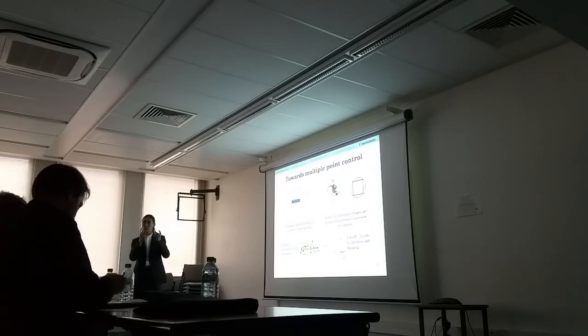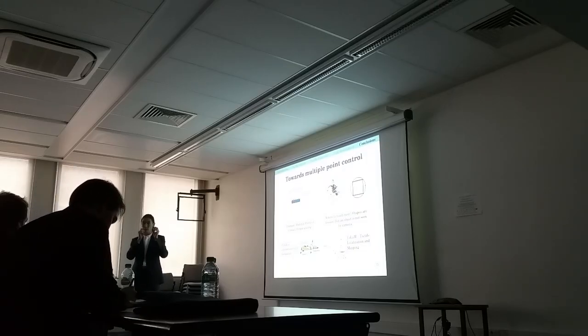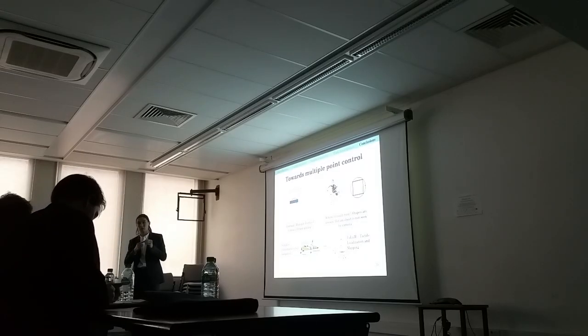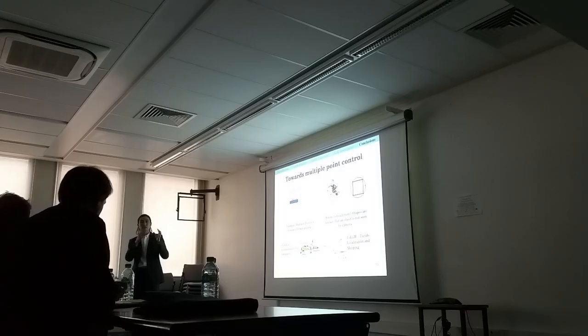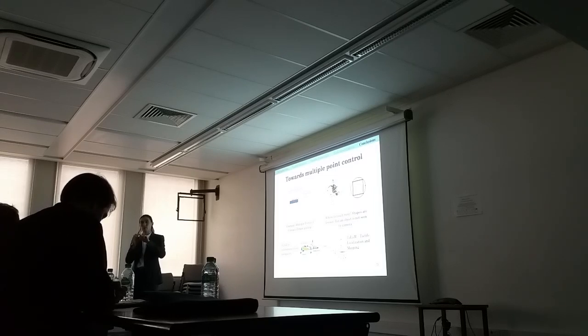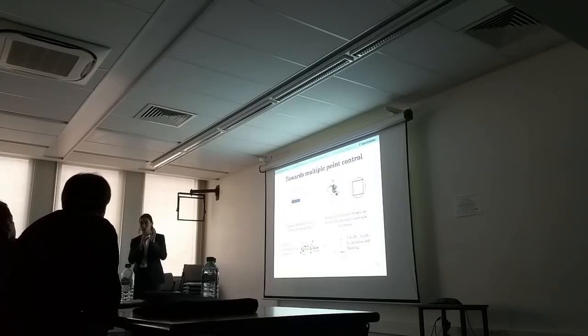Here we can map the center of contact that we calculate from the BioTac sensors to the rotational motions of the fingertips using this projection matrix. And if there are several of these tactile sensors on the fingertips, then for each finger we would have this tactile controller, and we can still control these features in order to perform different tasks applied to the environment.